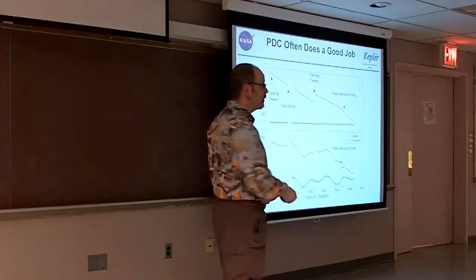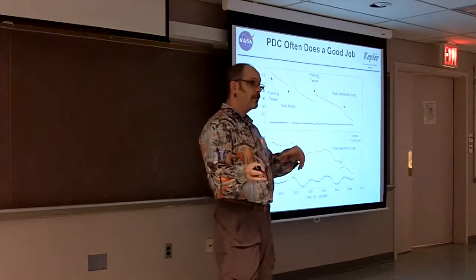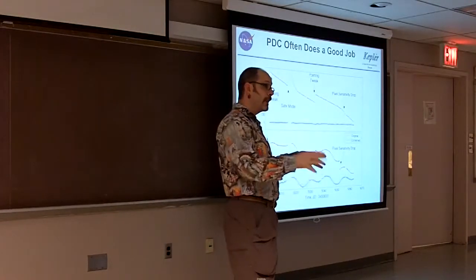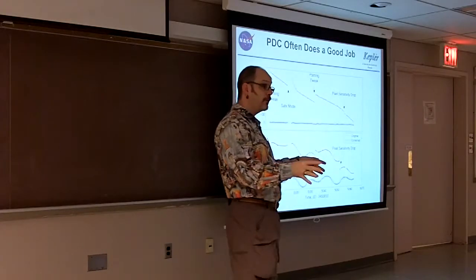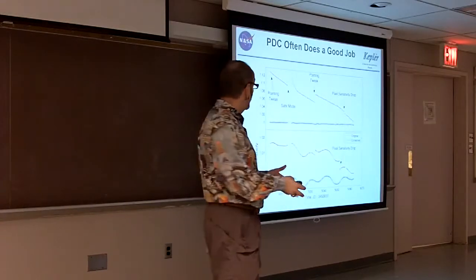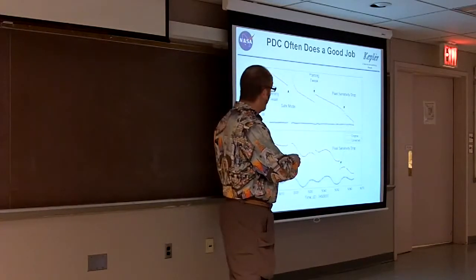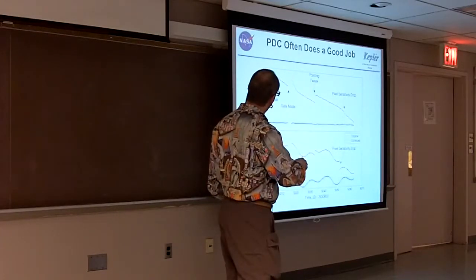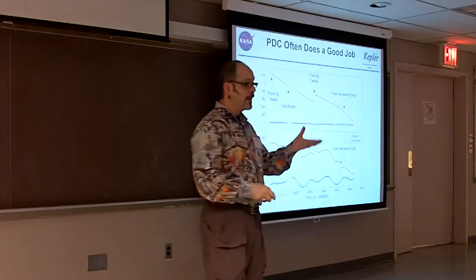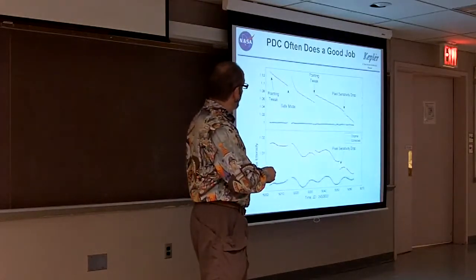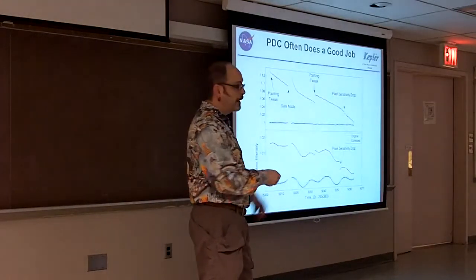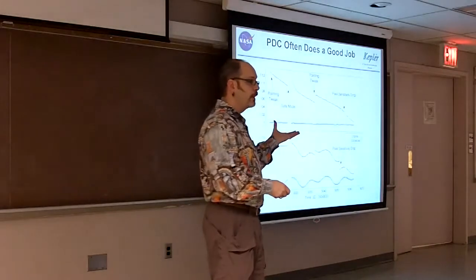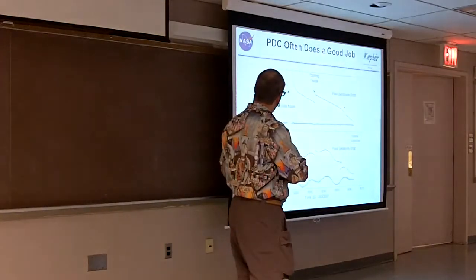And we had some safe modes, and during these early safe modes, we turned off the photometer so it cooled down. Principal heat load are the CCDs and the associated electronics. So turn the thing back on and it heats up. Well, even though we had, quote, equilibrium, you can still see the thermal signature 4 or 5 days into the data. So our algorithm has to deal with these operationally induced thermal signatures or other signatures in the data.